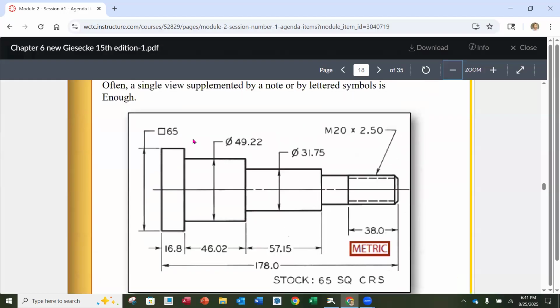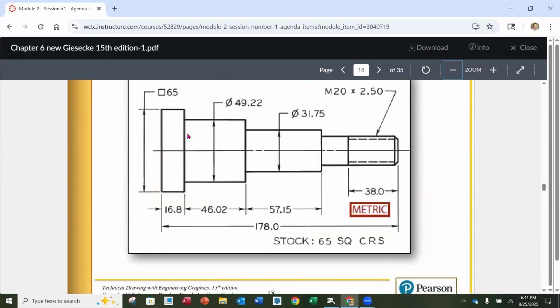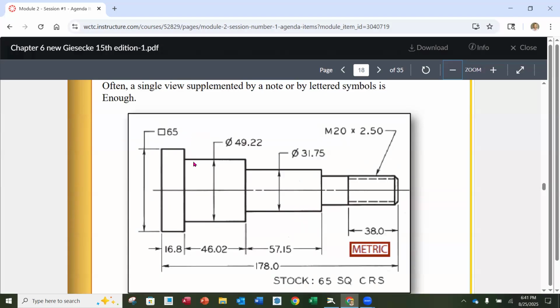You might be like, well, it was there. They're going to be like, well, I didn't see it. And now I've got to remake 4,500 parts. I don't know, however many, but they're going to be scrapped. They're not going to work. So it's really important that we're very clear and draw an extra view. I just can't emphasize this enough. Designers, CAD operators, engineers, they draw this drawing once. Take the extra time, 5 minutes, not even, a couple minutes to create that side view and dimension it appropriately. Now you're not going to have misinterpretations down the line that could cost money.